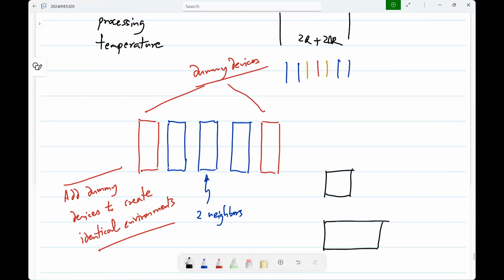So that you can count from 0 to 2 to the 10 minus 1, right? That's a very big ratio, about 1:500, but that's actually not even the most complicated digital to analog converter you see. You can have 12 bits, and this increases exponentially with the number of bits. So you can have components with very different values, with very large ratios, and you have to be able to make them precisely, and all these things become very important.